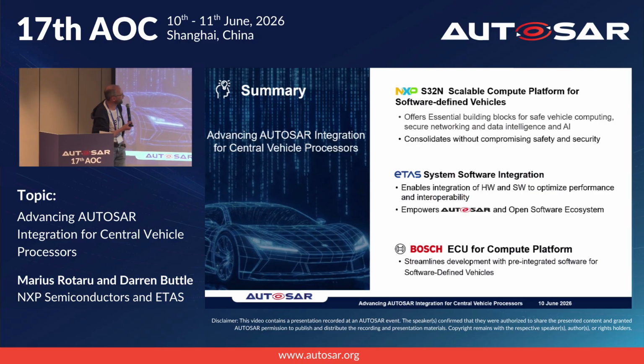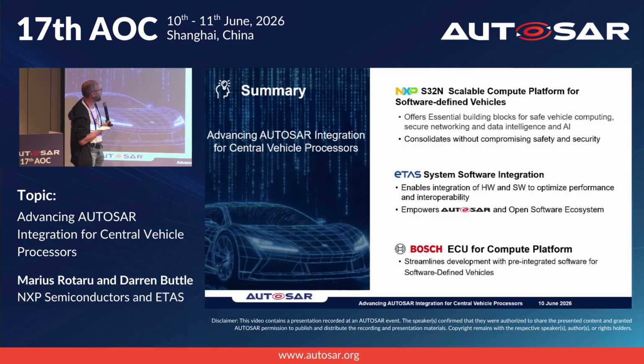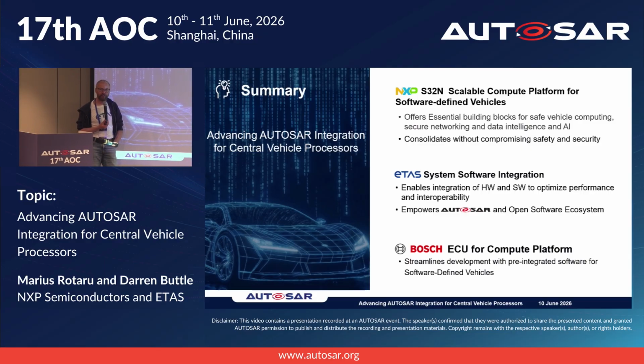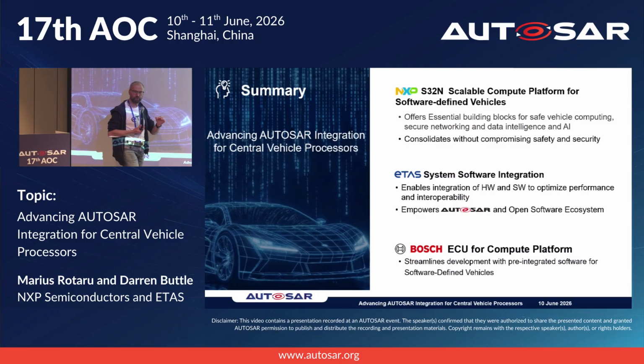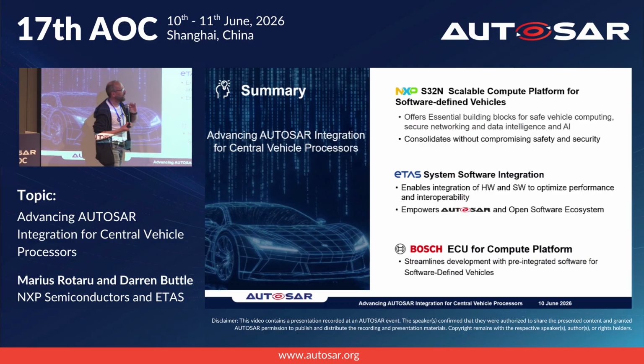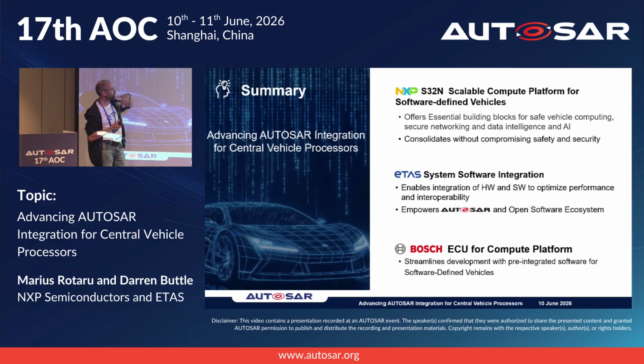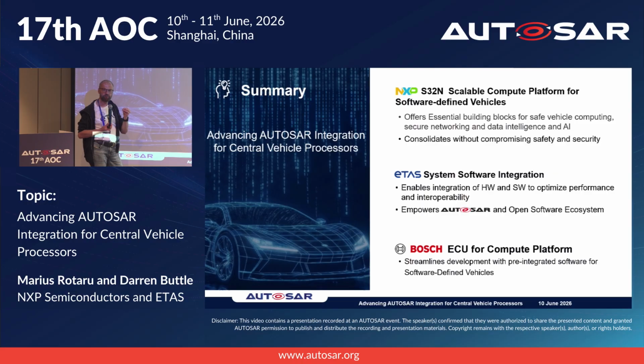Okay. So there's three parts of this. So the first of it is essentially that software controllable, configurable part of hardware. So that idea of being able to create individual cohorts, to have a set of peripherals in the hardware, a set of CPU cores in the hardware, and some faster and slower models of communicating between those cores. But then being able to basically build your own chip out of those building blocks in hardware by configuration of the hardware virtualization. And when you're setting that up, then it allows you to then do this without compromising safety and security, because a lot of the things that you might traditionally do in a more software-driven hypervisor environment, you're doing that by setting up a set of registers in hardware.